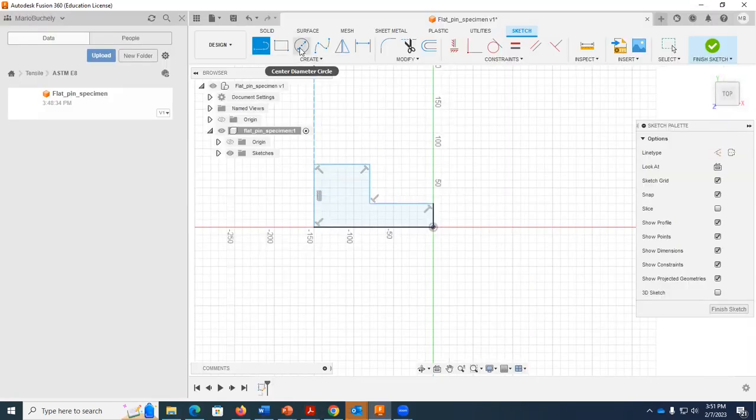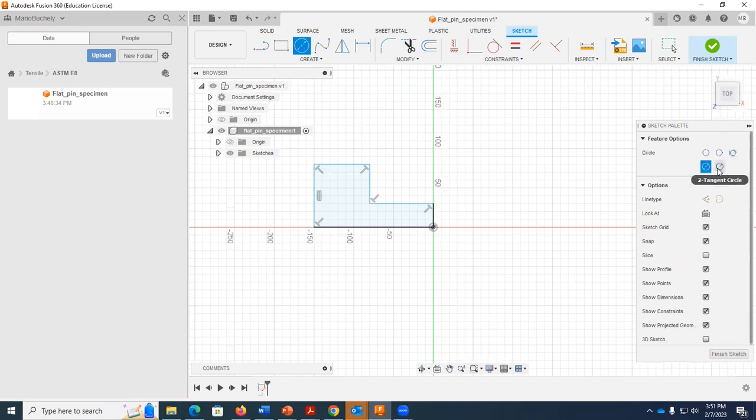So basically what I do is I select the circle profile, and I have different options to create circles: circles by diameter, clicking in the center, circles by tangent, so I can select whatever I want. What I want to create is a circle by tangent. You see it's giving you different options, and when you click it, the small box gives you notes on what to do. It says to select the first tangent of the circle, so it's going to be this one. After that, I'm going to take this as a second tangent. So you can create your circle that way.